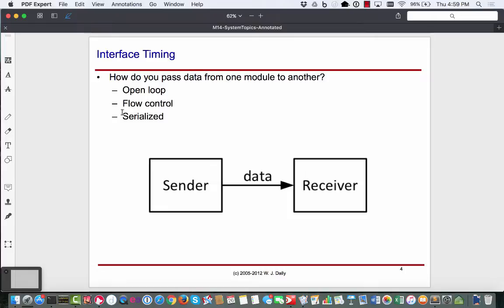Unfortunately, with long-running traces or wires of interconnects, the delays can be very asymmetric. Since they can be asymmetric, it's kind of like a skew, so then we have to budget for it, and that becomes a problem. So it's much easier to send data at a high speed over a single wire, because then I don't have to worry about the skew between bits. Okay, so you would see that our high-speed interconnects are all kind of serial. Okay, just pump things out.